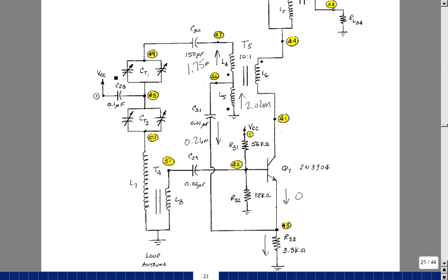Now all of this is happening relative to the tuned circuit on this side. So we're creating a lot of harmonics, but the only signal that comes through from this side is a single 1.08 megahertz signal. Take a look at that in the simulation. And that's how the oscillator perpetuates itself. If you were to change any of these dots, the oscillator would actually die out. So the dot notation here was important because of how it works to maintain this feedback loop. It starts to go unstable, but eventually shuts itself off. So what we're going to get is a series of pulses in Q7, the frequency of which is related to the tuning of this coil.